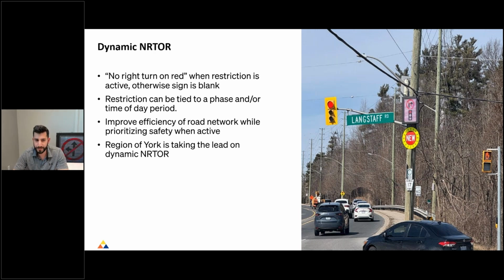So again, this is the method which is going to take into consideration the delays and queue lengths that are occurring because of the static no right-hand turn signage, but also prioritize safety benefits for pedestrians from conflicting turning movements. Now, the main problem with this application is that in the past, there really wasn't a consensus on enforcement.